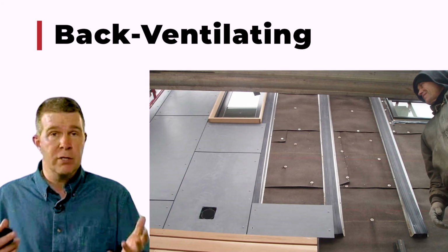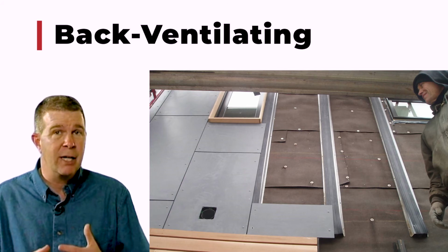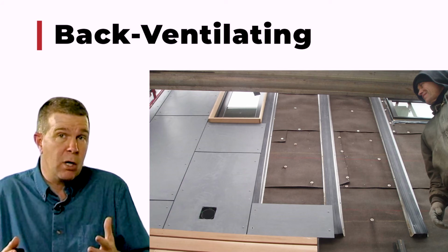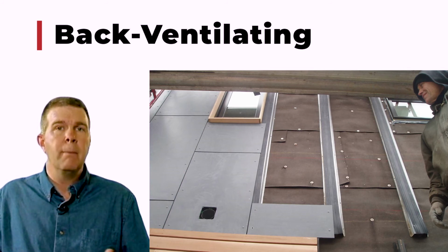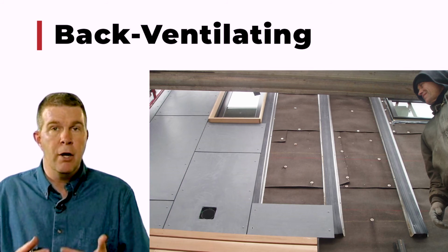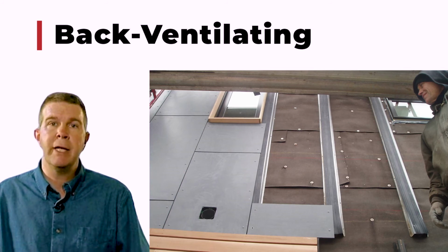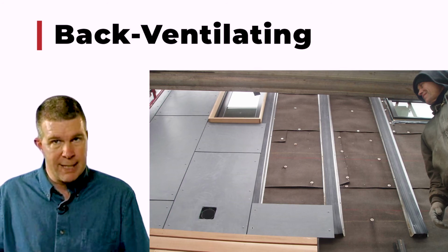We can always know that siding, every type of siding is always going to leak, and that's important. If you understand that it's going to leak, plan for it, allow for it. Know that you need to have a proper drainage plane behind it so that it can take it away, all right?